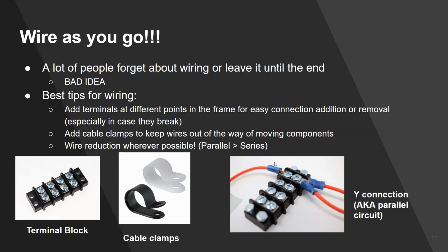Whereas a parallel circuit, which is the one we have over here, where these red wires are all positive, is coming from the positive terminal of your battery, and then it's going to two different systems, and then you have a matching one coming back. So two coming back from the negative, going to the negative of your battery. That is the best possible thing, because if this wire breaks, the other one can still have current from your battery. The only time it becomes a problem is when the wire coming directly from the battery breaks, but in that case, it would have been a problem regardless, because then it's the one coming from your battery that's broken. So this is a good system to have.